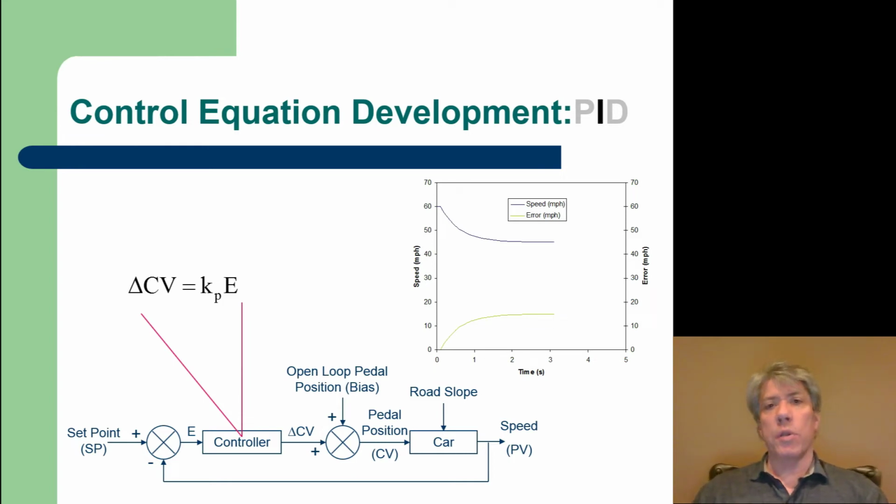So what's the solution to this problem of non-zero steady state error? Notice that's what's happened, right? If our proportional gain is high enough to be useful, well, it might be so high that we get oscillation. That's not good control. But we can never eliminate the steady state offset, the error at steady state. We can never get the gain high enough because it starts to oscillate. So the proportional only controller suffers from non-zero steady state error. That's the problem with proportional control.